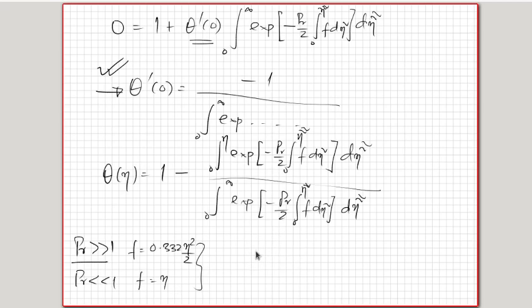So what you would get is for Prandtl number much greater than 1, you would get a point Nusselt number is equal to Rex to the power of half into theta prime at 0, and that will give me 0.565, which is actually 1 over root pi, okay, multiplied by Rex Pr all to the power of half for Prandtl number much less than 1.